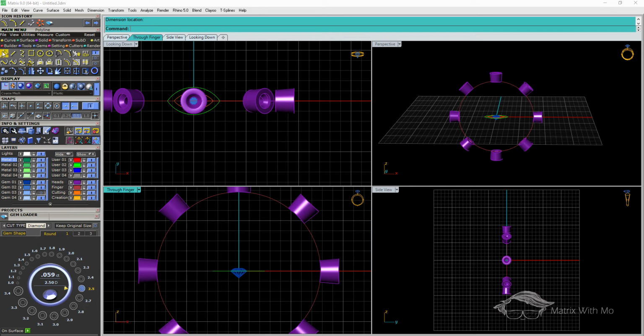To do that, I will just draw a line representing the height of my marquee shape here, which I decided I wanted 2.4. I'll do a rotate with this from this point to this point with an angle of 10. So that established my angle of my marquee. And if I want to, I can mirror this over.